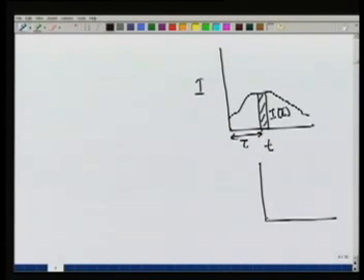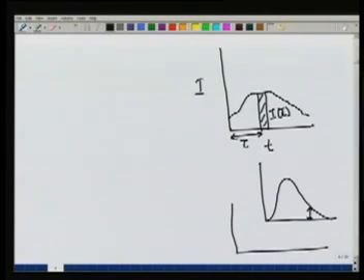Now if we draw the IUH starting from this point tau, and want to find out the DRH at any particular time t. So our aim is to find out the DRH ordinate at the point t, which we will call Q(t). Now this Q(t) is because of this rainfall intensity and this IUH. And if we draw the IUH starting from this point as origin, that means the direct runoff due to this strip of rain can be given as